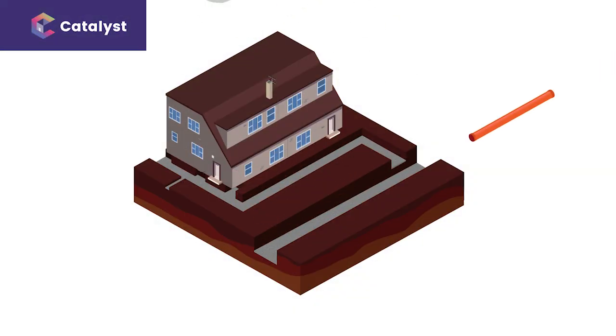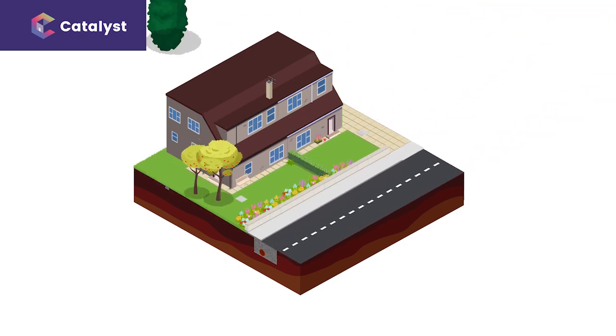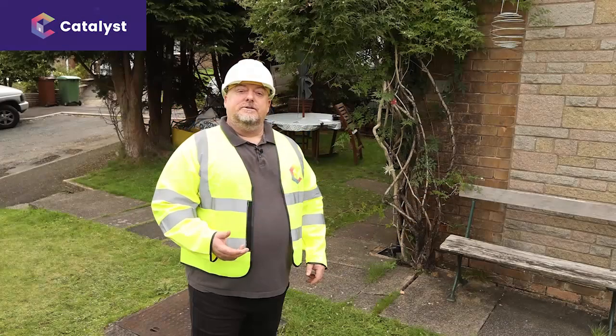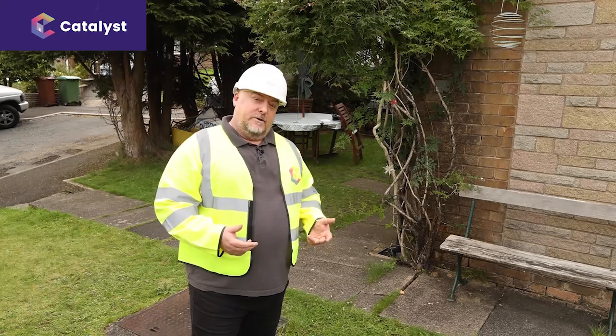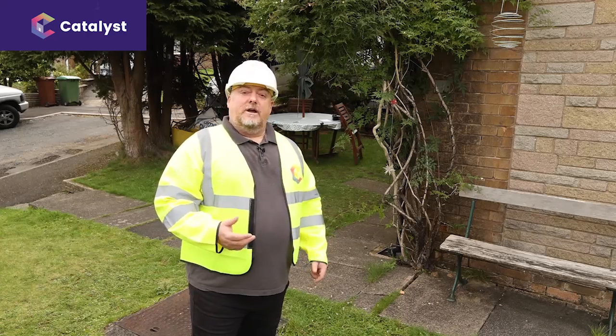Today's site is a semi-detached property built in the 1970s. The scenario is that there is cracking and downward movement on the front corner. Previous investigations by Catalyst have suggested that there is possibly a drainage issue. A CCTV survey has been requested.